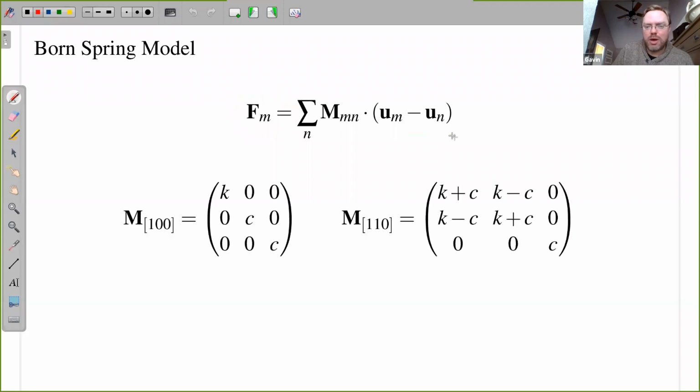Just like you'd expect from any spring. And the matrix then is just the matrix that contains all these spring constants. So for example, in the 1, 0, 0 direction, you would have the stiffness as you pull it in that direction, K, and then you have the stiffnesses perpendicular that try to penalize the rotation or movement away from that direction.